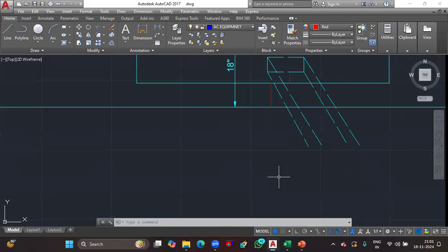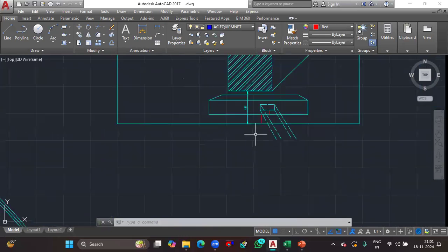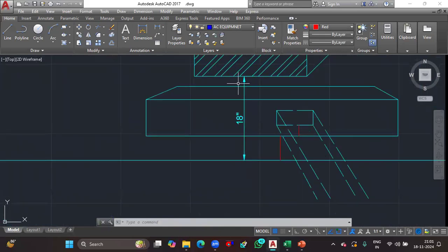So the length of the dropper duct depends upon the clearance area that you've been provided. In this plenum area, the clearance has to be 2 inches on top side and 2 inches on bottom side. That's how you got 14 for the duct height, isn't it? But in the case of collar duct height, it should be 10 inches. That means from the main duct height, you consider 2 inches on top side, 2 inches on bottom side. That's how we got 10 inches height, isn't it?